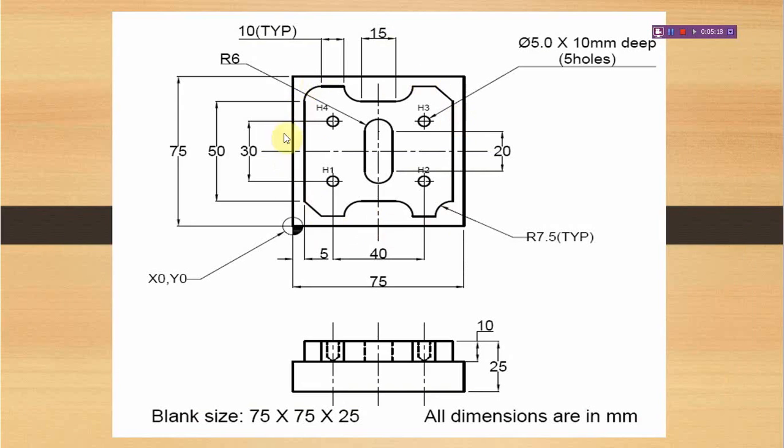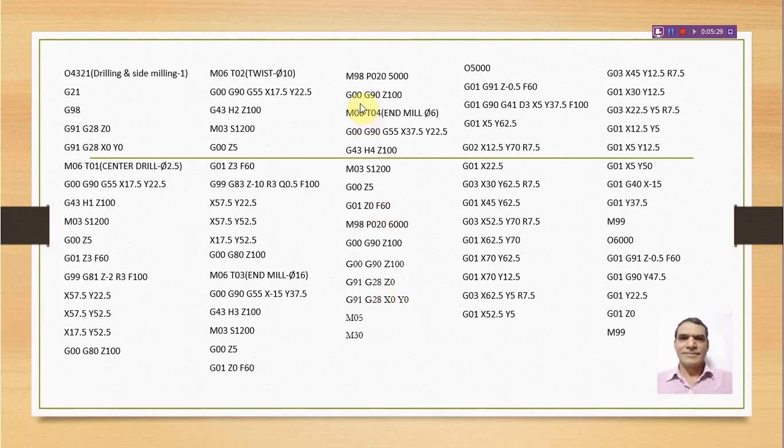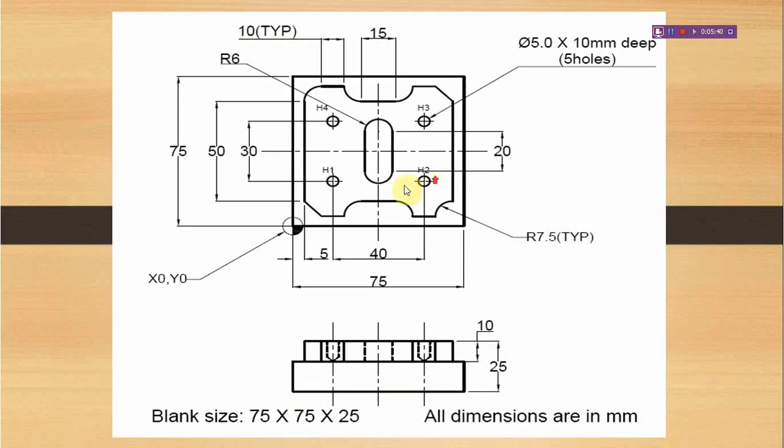Say 20 times the tool is rotating by giving 0.5 mm incremental depth of cut, so that we will get a 10 mm total depth side milling operation. And then simply moving the cutter up. Then one more tool we are calling, T04. This is for slot milling.